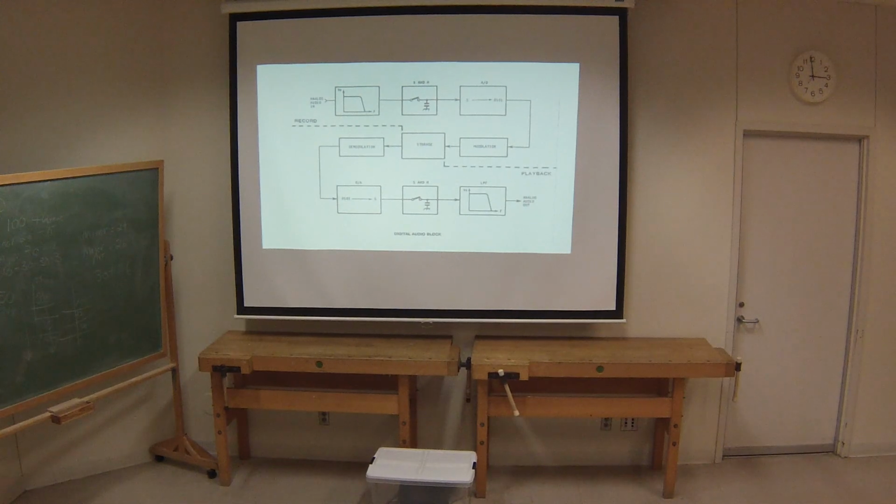And at this point right here, if you were to tap the signal, amplify it, and listen to it, you would hear audio. It might be a little rough, but you would hear audio. And then we take these pulses and put them through a sample and hold circuit, which is timed to the pulses, and this is where the time constant is longer.